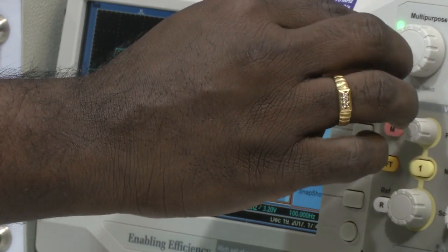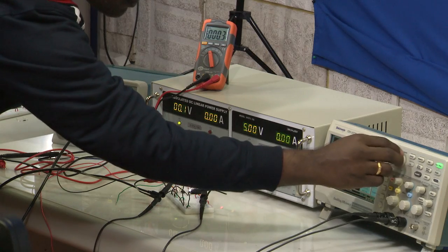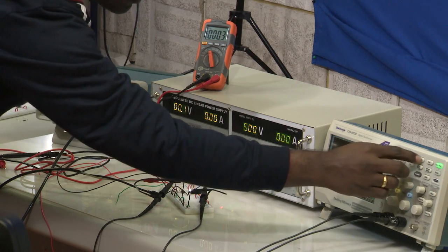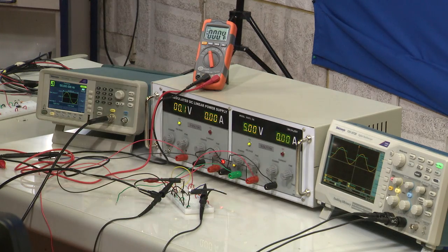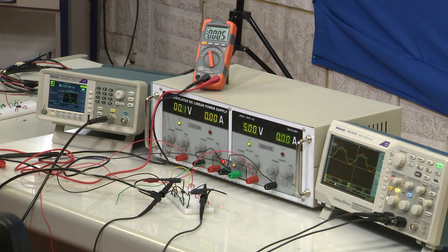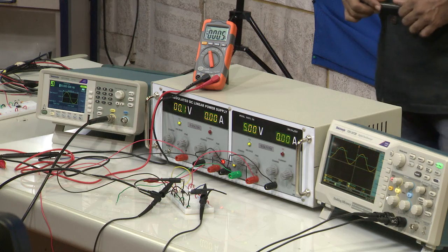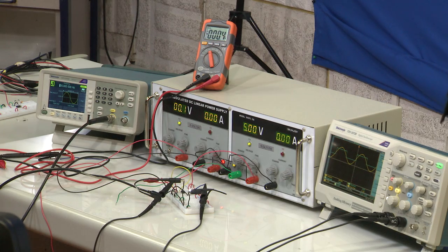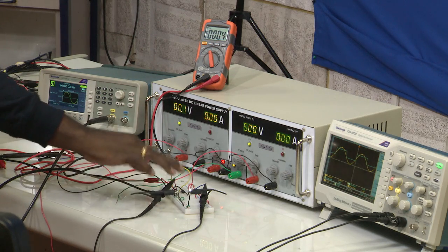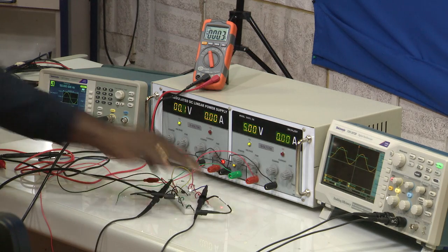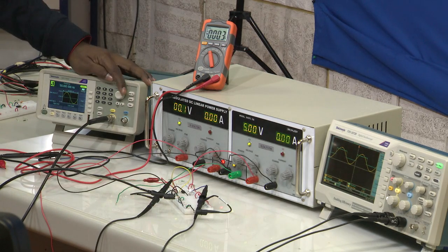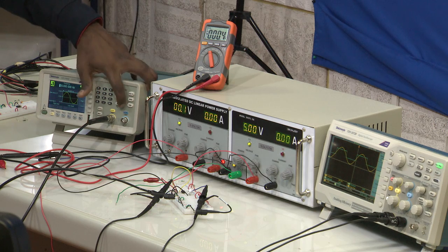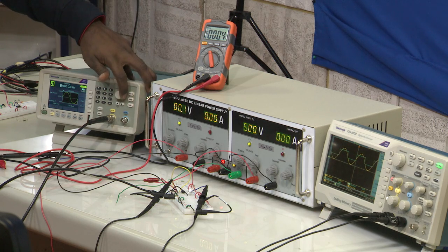What is it? The square wave. That means that even if we apply sine wave, the output is what? 0 and 1. Indirectly we can say output is nothing but 0 and 1, that is a square wave, right. So, this is the beauty of the comparator, that your input signal is sine wave, your output can be square wave,